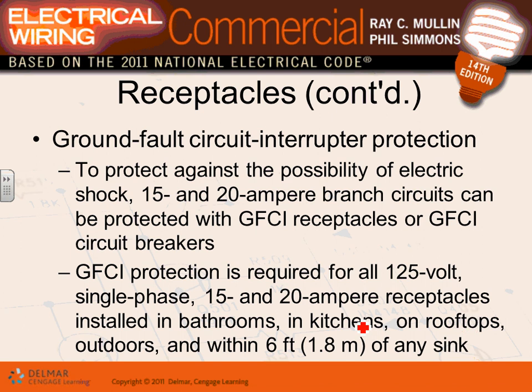Okay, moving on from the receptacle. So when you deal with the receptacle for our project, Adam, when you start laying out, there are two types of receptacle. One is technology, where they're going to have an isolated ground receptacle and its own neutral, no shared neutral. That's what we're saying, and they're going to be on a different circuit. That's the technology receptacle, an isolated ground receptacle. There's the rest of the other receptacles, which are regular commercial grade receptacles, which basically have one ground instead of two. Now moving on into the commercial project, guys.